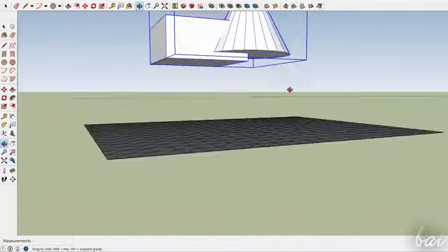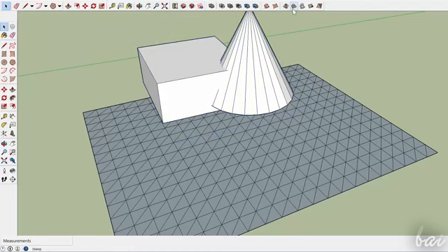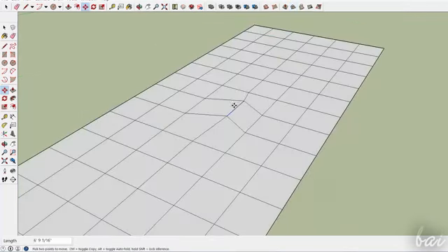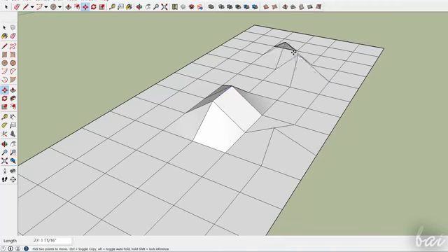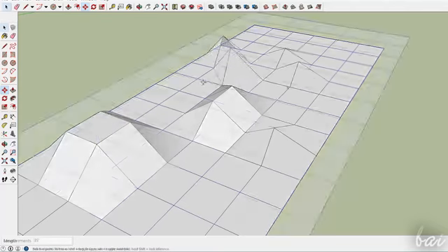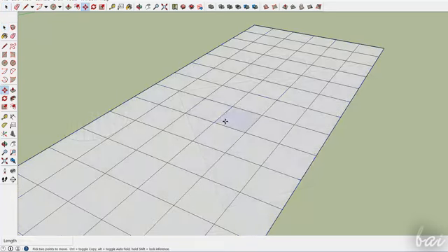Mind that the Sandbox tools work on objects that can be divided in multiple triangles, so you can use these on polygons, rectangles, or any filled closed path that lays on a single plane. If you want to edit mesh objects in detail, you must first explode them to extract all its triangles or rectangles. Just right-click on the sandbox and go to Explode. Mind not to take sandboxes too large, or your computer may lag quite a lot.